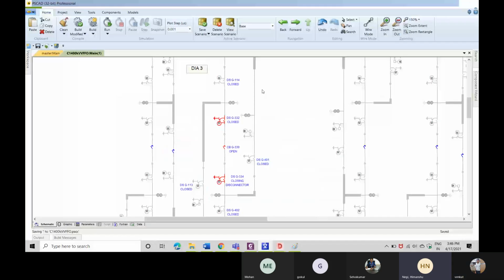And I think to understand that, first I need to understand the theory in a greater way, like how this disconnector operation works. But like you said, when you open the disconnector, before that you open the circuit breaker, and that's what you want to measure the voltage on the open end to make sure that circuit breaker will be kept open.